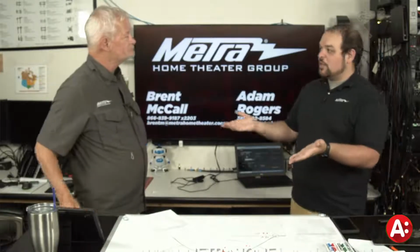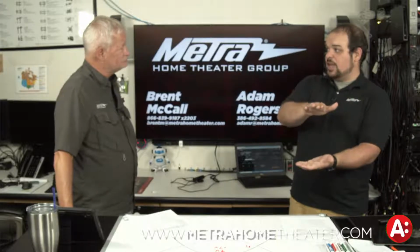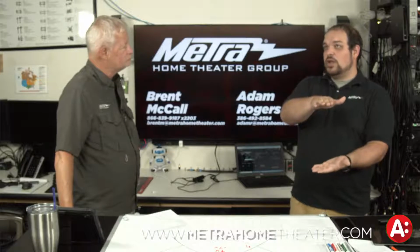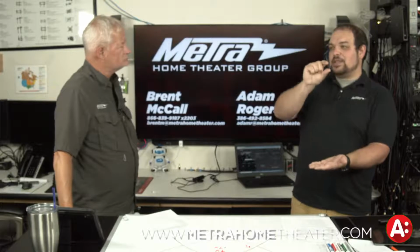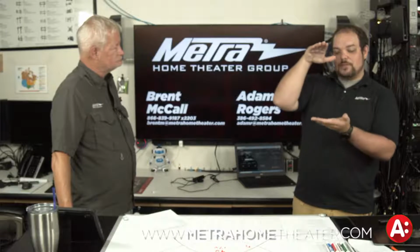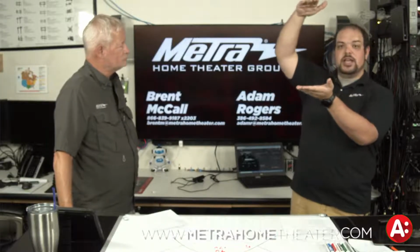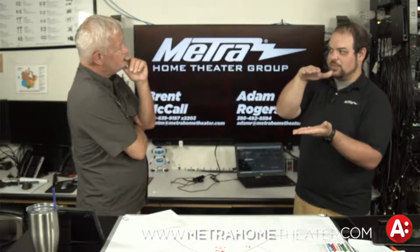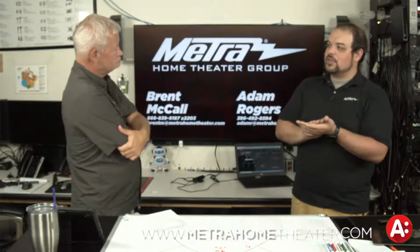Exactly. So that's where we come into play, where we have the differential. The voltages may start at 47 volts, and then from there, the difference between 47 volts and, I think, PAM10 uses a total of 10 steps, or 16 steps for PAM16, but the actual voltage difference is only 5 volts. So what they'll do is they'll take 47 volts and go up to 52 volts. And then they have 47 to 52 volts to use for the data transmission. And that's where they break it down into the different steps. That's where they break down those 5 volts into 16 different layers.